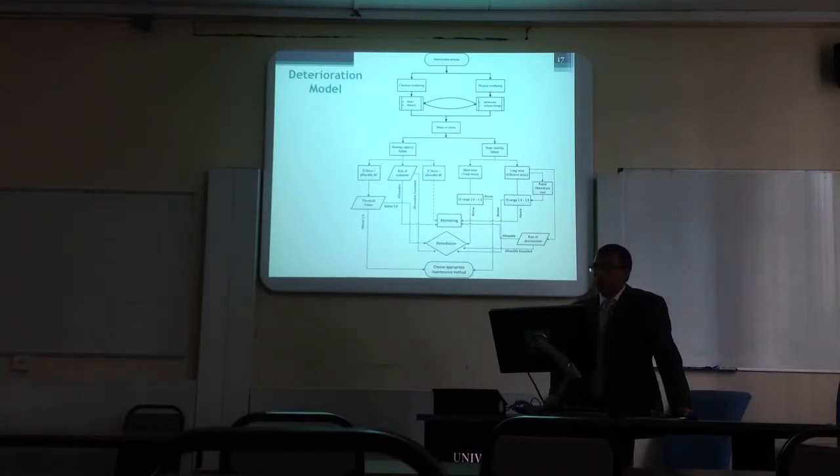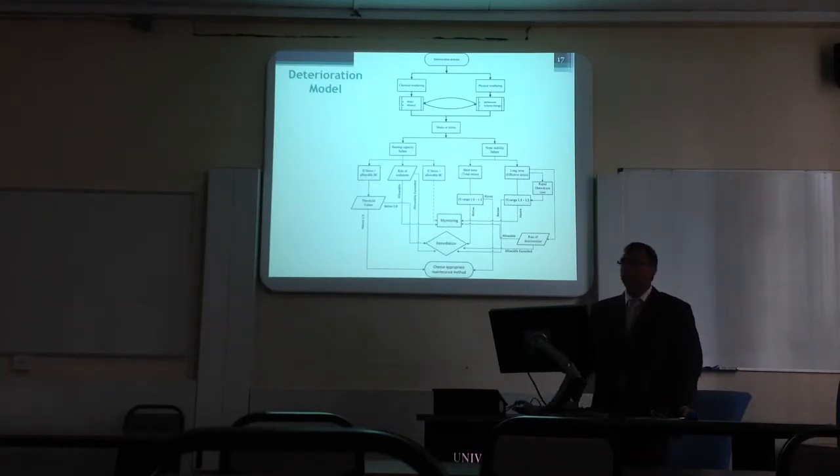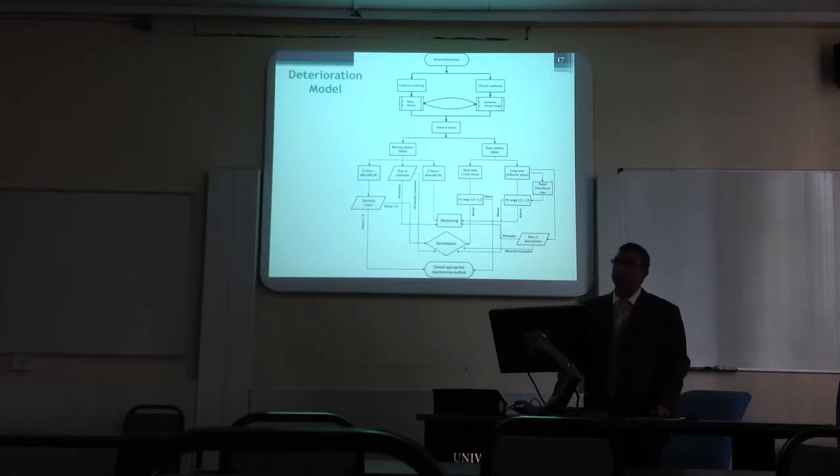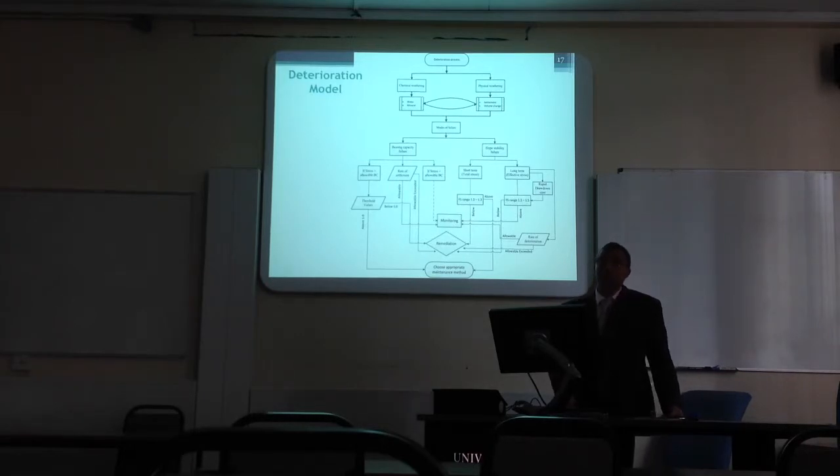If it is above, however, it is mentioned factor of safety 1.3 to 1.5, but it can go up to 3. It depends on the slip circle, or the location of the weak strata. Getting the rate of deterioration is a bit cumbersome, because the rate of deterioration will depend on the age or the time of soil deterioration. So it needs further development to ascertain how the soil will deteriorate with passage of time.